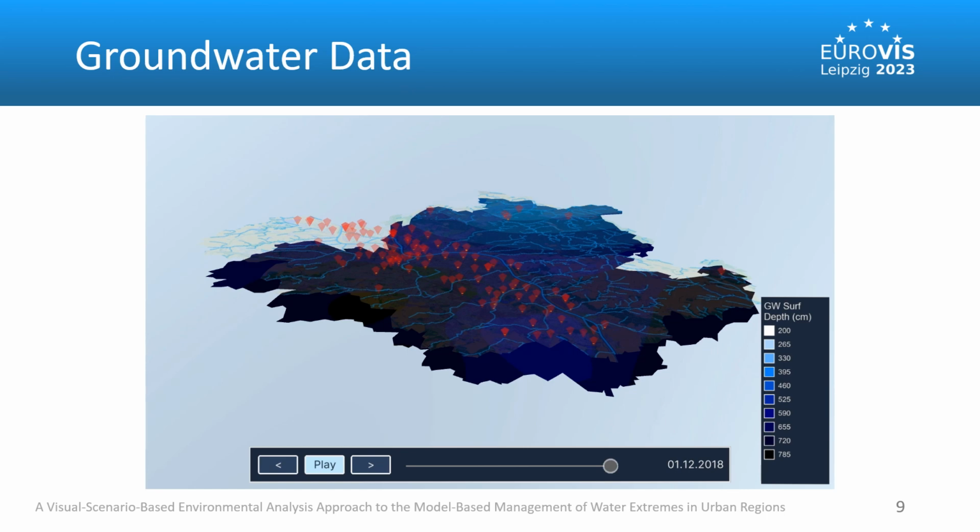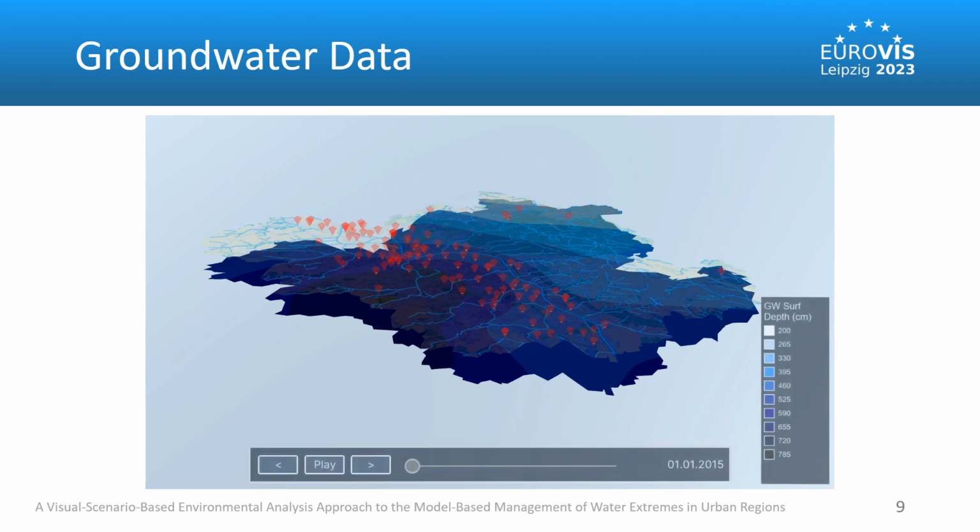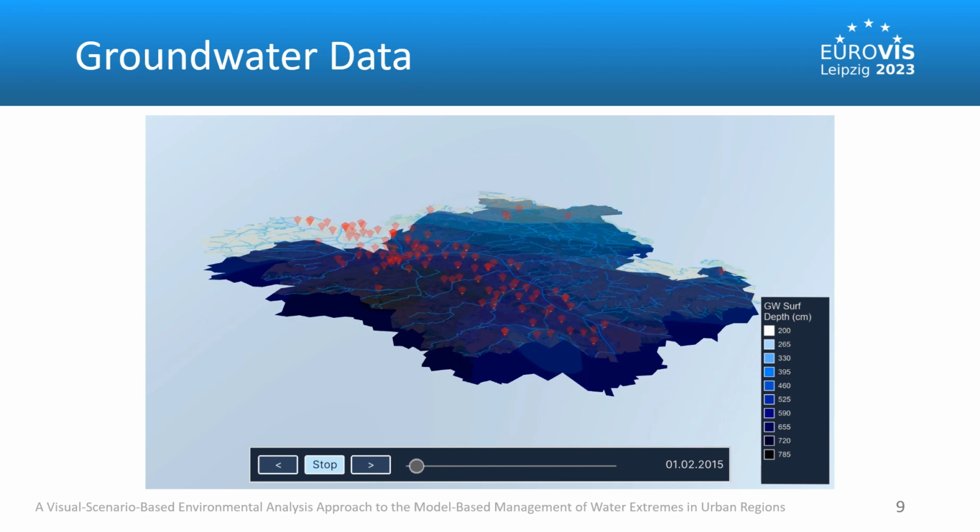To construct a special 3D animation of the data, we first sliced the filtered data regarding their measurement dates and created 48 sets of groundwater measurement data of all the stations. Then we spatially interpolated using the kriging method to create 2D raster data of interpolated groundwater head levels for every time step.